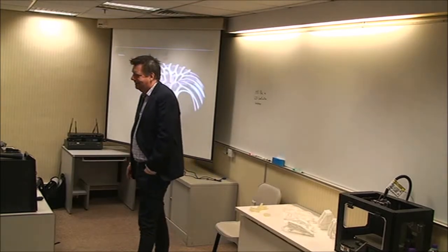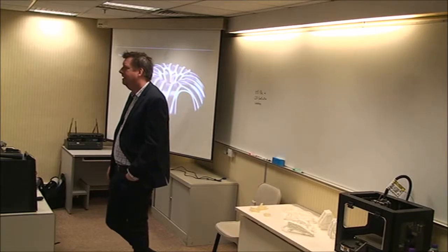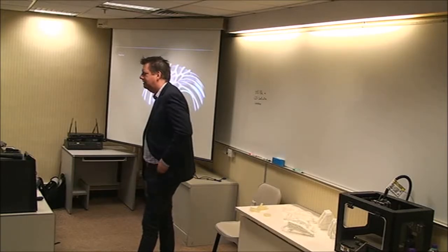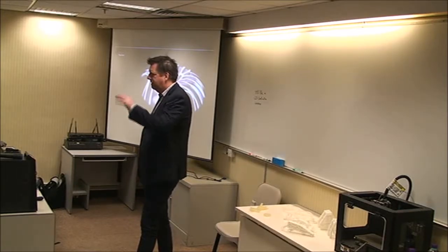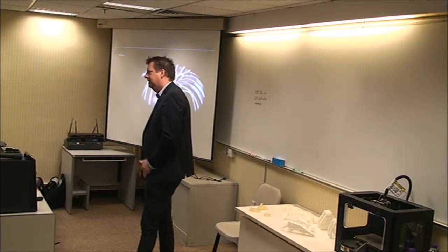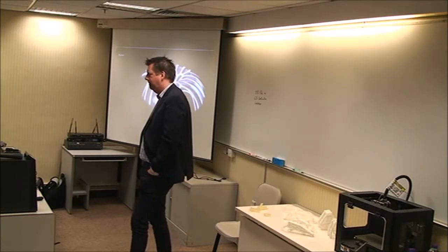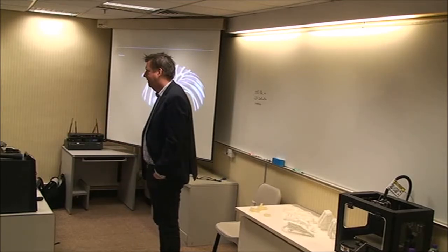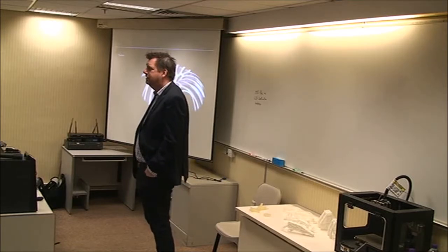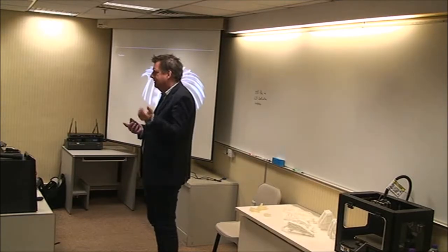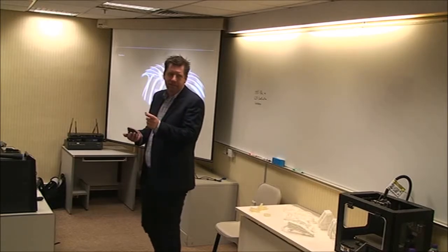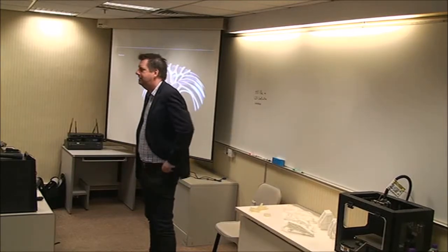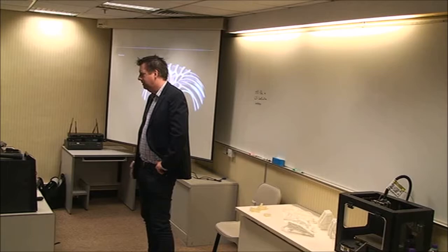This was just an idea of a pavilion study. So imagine a sort of superstructure with glass filling in. That just started off as a very simple dome structure with wind loadings and gravity loadings on it, which came up with that kind of white frame, and then I just sketched over it in PolyNURBS. Again, the whole process probably took an hour. So it's just a thinking tool. I mentioned the minimum dimension of things. You get very different designs as that changes. So you can play with lots of ideas and come up with cool concepts.